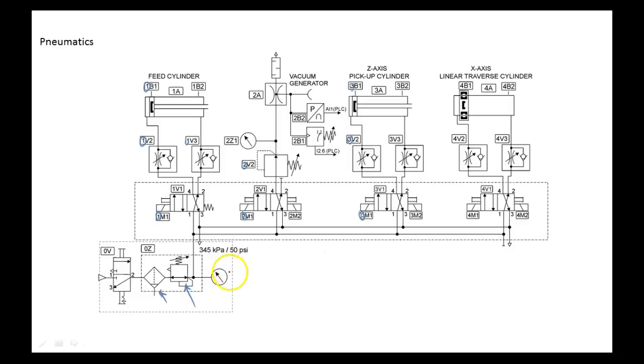Of course, what do you think this is a symbol for? It didn't look. That's a gauge. Okay, so that's the pressure gauge that's part of the service unit. Then we move up here. So this is circuit 1. It consists of a directional control valve. Okay. It's a four-way 2-position valve. Now the way it's nomenclatured is kind of weird. They say a 4-2-way valve. So they say, even though 4 is, when they talk about the ways, that's the number of what? Ports. That makes sense. And we've got stuff hooked up to it.